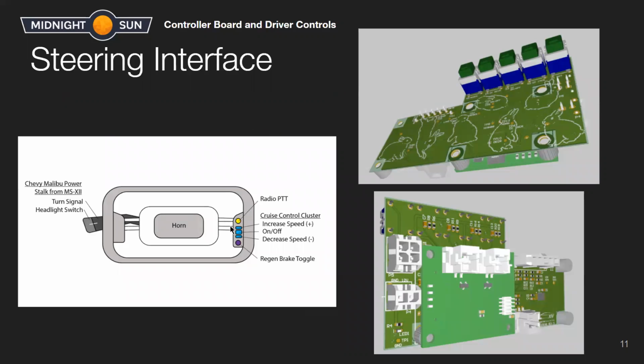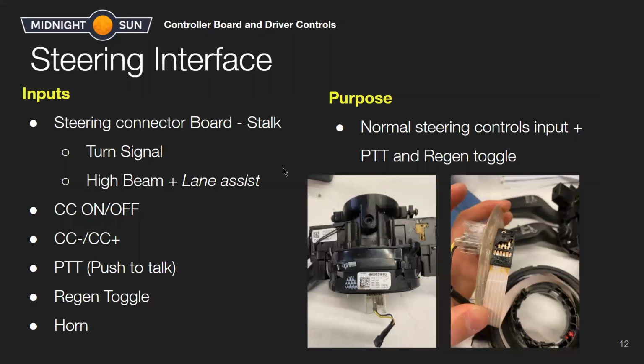And then something interesting for steering and the design of how it works: everything sits on the wheel, but the wheel is turning. So how do you have nice cabling? If you were to just dangle cables, as you turn your wheel, your cables would twist. So the solution to that is having a clock spring. You might have heard us talk about this because we have to replace the ribbon cable in our clock spring.